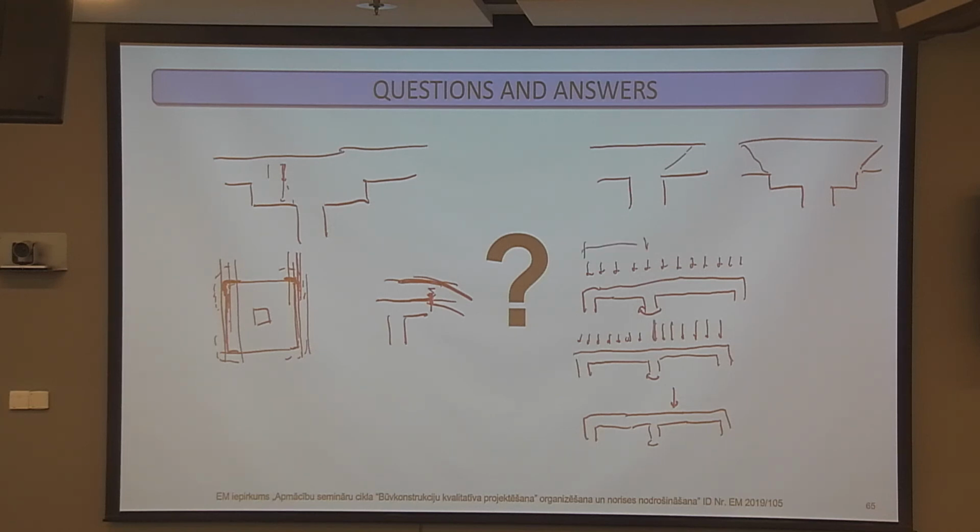Or you have different loads, the spans are the same, but you have higher load on one side. This is different. And then when you have just a large shear force close to the perimeter, even if the moment is the same in all the cases, the distribution of shear force is not the same, and Eurocode doesn't distinguish between these cases.